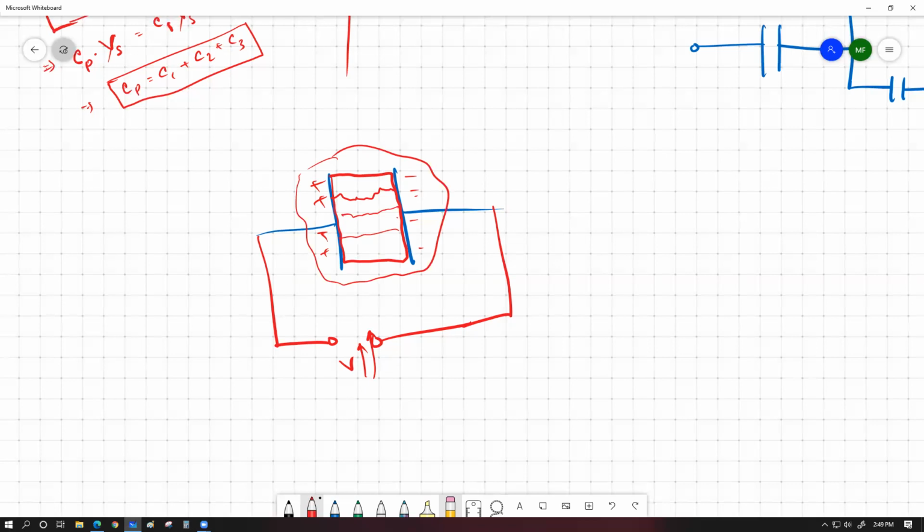And if this actually happens, that electrons start to flow, you have to understand that whenever lightning happens, a very high voltage produces a very high current over a very small amount of time, and the heat generated by the electric current is given by P equals I squared R. This is the electric power form of the equation. So the heat energy converted can be given by I squared R T. This T for a single spark is actually pretty small, but the I value for a single spark can be pretty large.